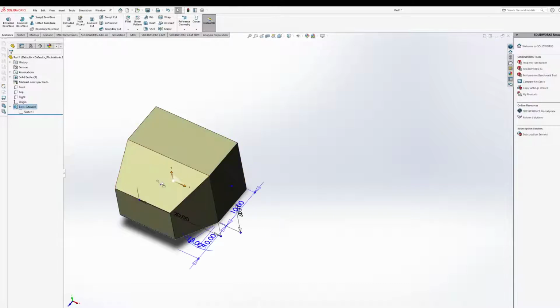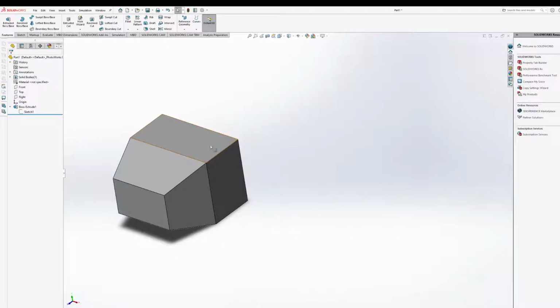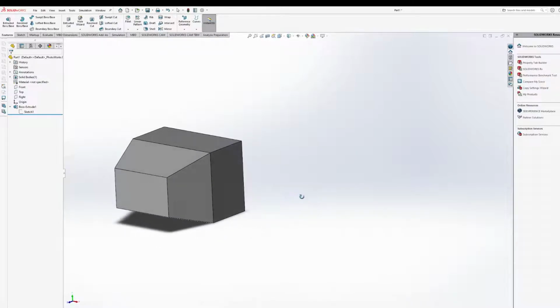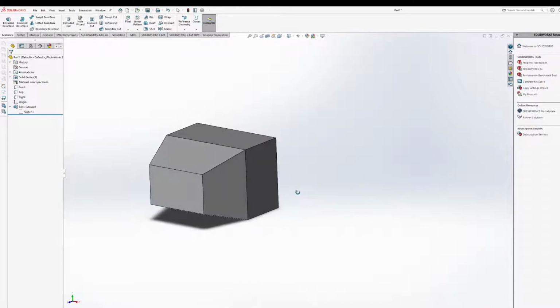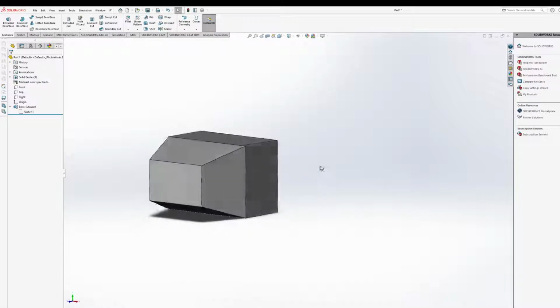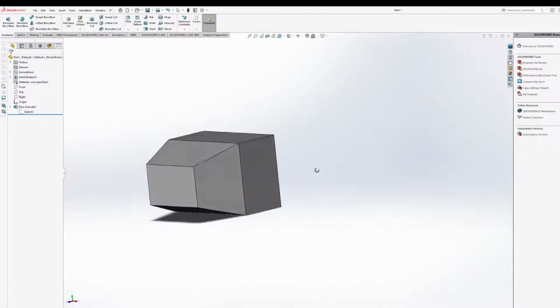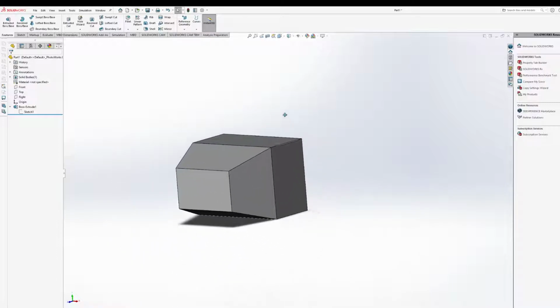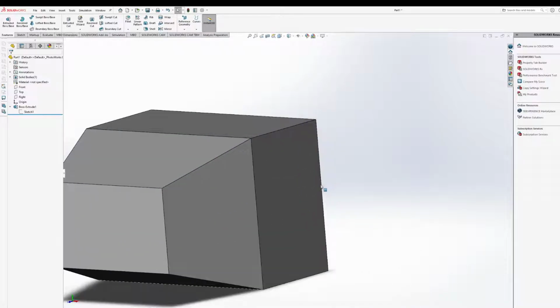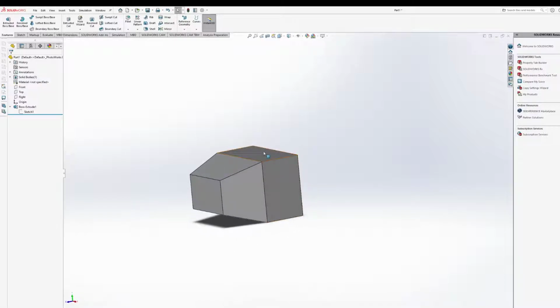As we can see, it's giving us other faces that we can work with. Moving the camera, if you hold down the middle mouse button, it's going to be a lot easier if you have a mouse, hopefully. Whatever your third mouse button is, if you hold that down, you're able to rotate it. If you hit Control and middle, you're able to move it in plane. Scrolling in and out. Should have mentioned that a bit earlier. That would have been helpful, wouldn't it?